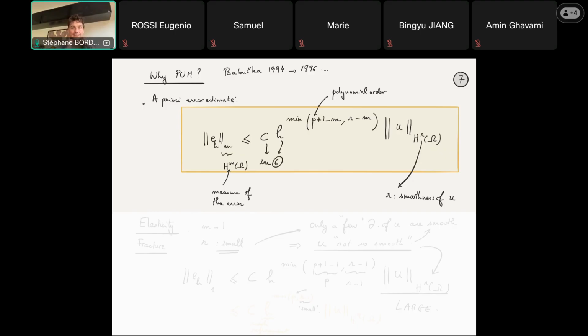They conserve mass and volume approximately on average because of what I said in the lecture last time, that you use an integral sign. That means that you integrate everything, which makes things easier because you decrease the continuity requirement, but also leads you to having an average solution, not a pointwise solution. So it makes things more stable at the cost of being exact. It's not exact anymore in terms of volume, mass, momentum conservation.